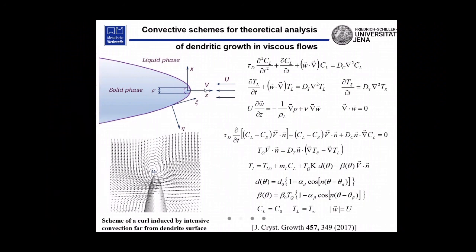And I told you, in principle, we can predict numerically and analytically these two main parameters, which are measured experimentally. The parameter V, velocity, is measured with a high-speed camera, and if the pattern was not transformed, we can expect that primary dendritic radii remain the same, and we can measure them statistically. We can say what the diameter or radius of the primary structure is as a function of undercooling. So this is a scheme.